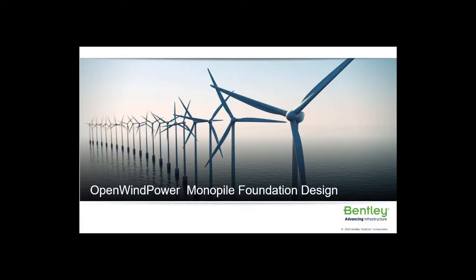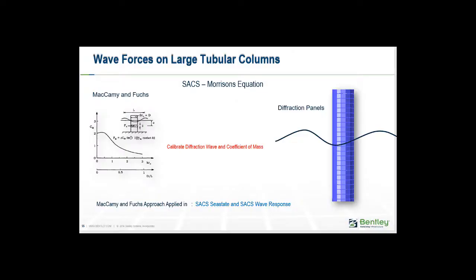Next, I'd like to discuss our monopile foundation design capabilities. And here, first we will look at the loads on large tubular columns. Essentially what we do here is we use the McCamy and Fuchs approach. What they did was they calibrated a wave diffraction model and adjusted the coefficient of mass to give you the same results as the diffraction model. And so this is applied for both in SEASTATE for static and wave response for a dynamic analysis.